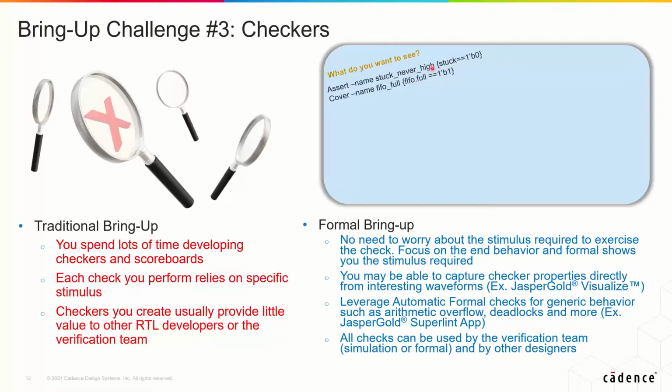You don't really have to worry about the stimulus. The tool will generate the stimulus for you, and therefore you can switch your focus, as a designer trying to bring up your design on formal, or as a verification engineer trying to bring up your setup on formal, to a more targeted approach, a focus on the end behavior.